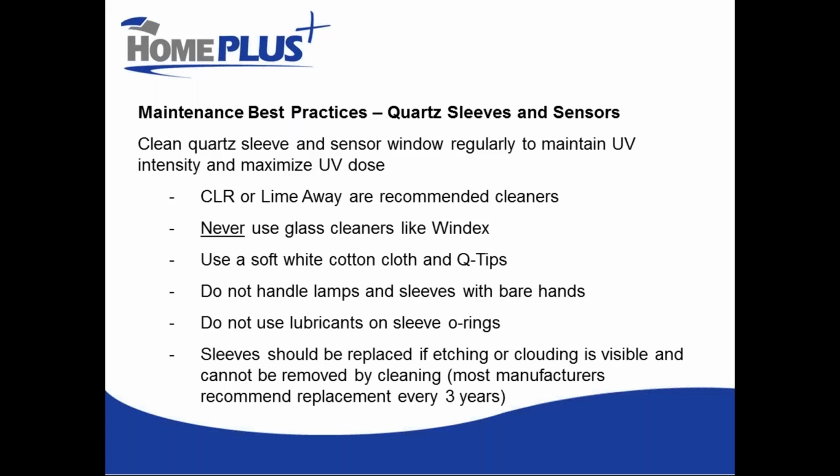If you don't have iron or manganese or hardness in your water, you very likely will not have to clean it nearly as often as a system that does, especially if a system has those things and is not pre-treating adequately for them. To clean the sleeve, it needs to be removed from the system. The recommended cleaner by most manufacturers is CLR. I'm sure you've seen their annoying commercials on TV. It is a very good product.